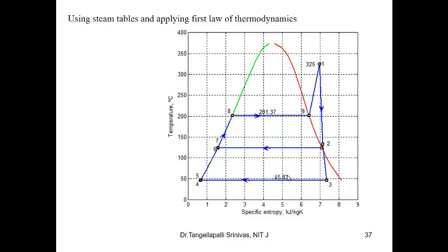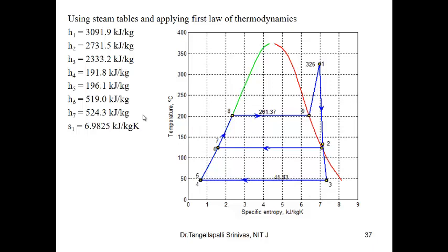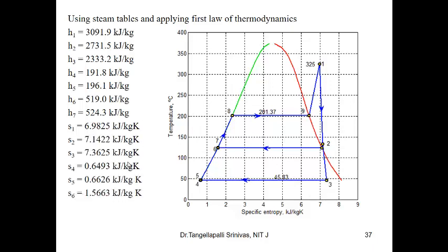Since the earlier lectures focused on energy solutions, the energy solution is not repeated in this problem, because this problem is mainly focused on the exergy solution. After solving the first law, the resultant enthalpies are furnished from H1 to H7, where 8 is a saturated liquid point. Similarly, the entropy values are also furnished here to solve the exergy of each and every component.